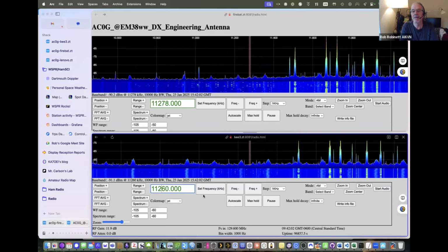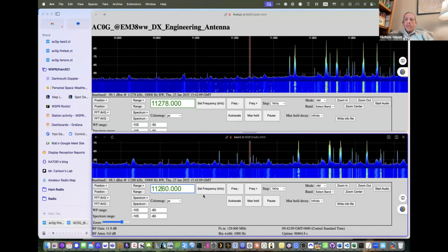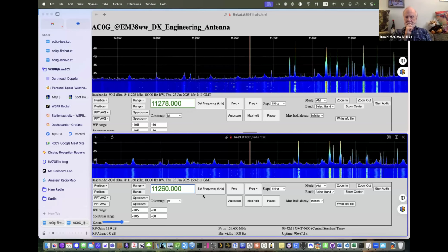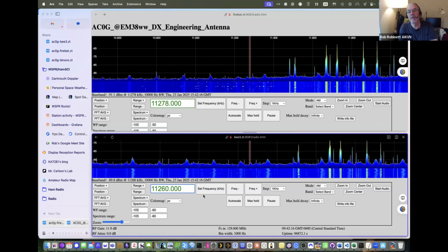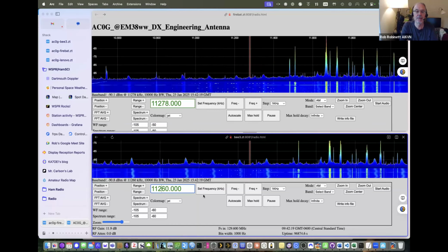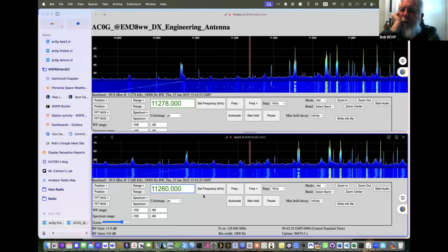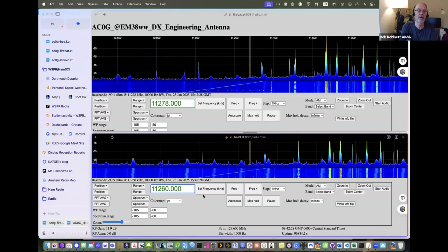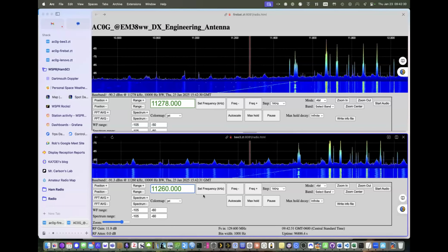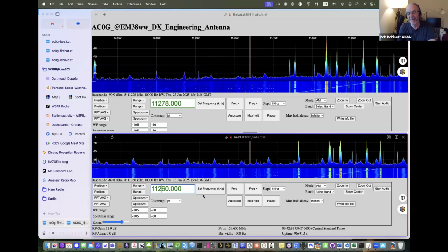Well, the DX Engineering one is powered through the coax? Yes. Okay, so that makes it difficult to put the transformer in it. Oh yes, of course. Both of them are. The DX Engineering has a separate option to supply the DC separately. So one thing you might do is go out and battery power the DX Engineering and see if this phenomenon goes away. We're going into this transformer.